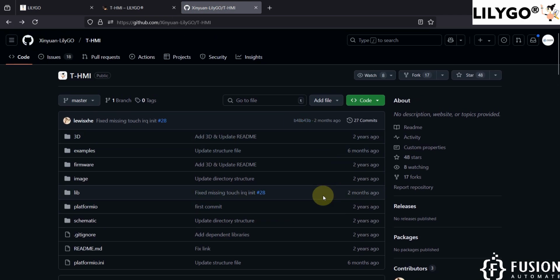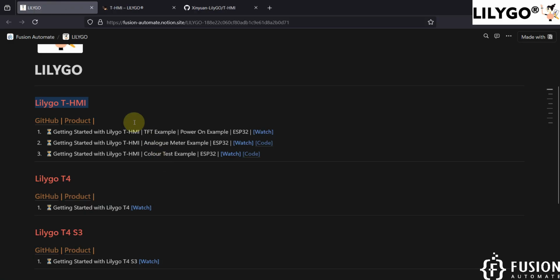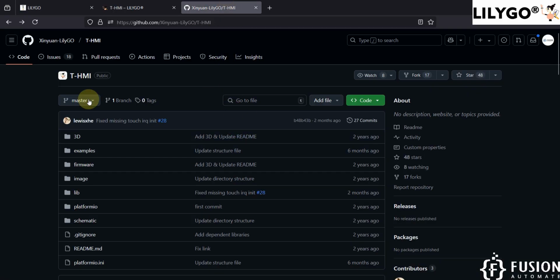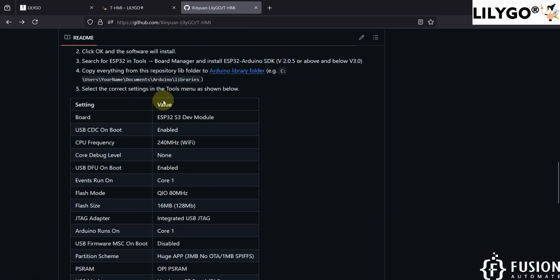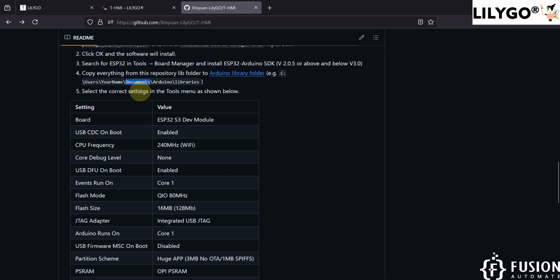Now in the very first video we covered how you can get started with it. If you want to get started programming the Lilygo T-HMI display from Arduino, you have to download this entire repository. You have to copy the content of this library folder to the Arduino library folder located in your Documents folder in your system.